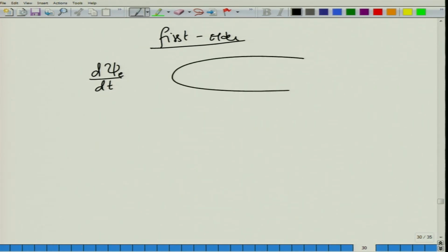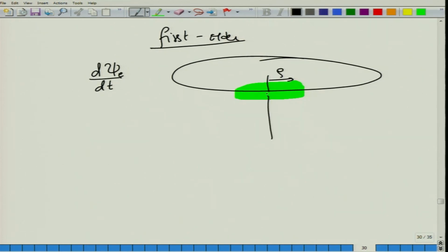So again, go back to the problem that we have. This is the top conductor, and now what I do is I consider a closed surface like this, which has a radius of rho, where rho tells me, so this central line is the rho equal to 0 line, and rho equal to rho will be the line at which this particular closed surface ends. There are charges, there is D of t, and surrounding this or coming out of this closed surface will be the electric flux psi e, which is the integral of D of t times the surface dS.